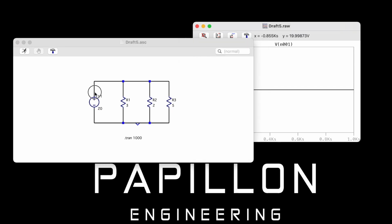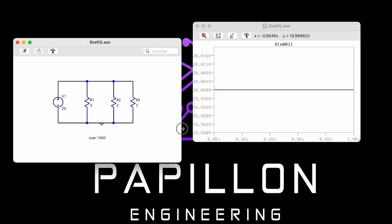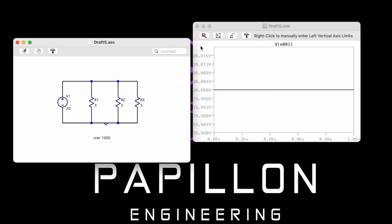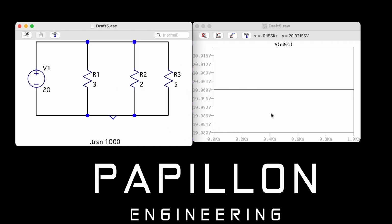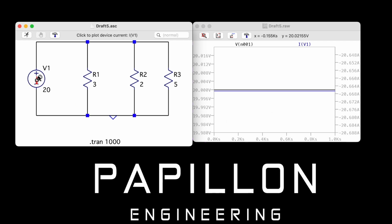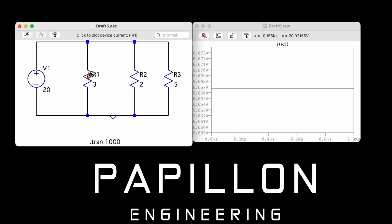And you notice on the scale on our plot, it shows that Vn001, which means the voltage of node 001. Let me just adjust the screen a little bit so you can see everything side by side to make it a little bit easier to visualize the results. And as we do that, again, I hit spacebar within our image so that we can actually put the entire schematic in frame.